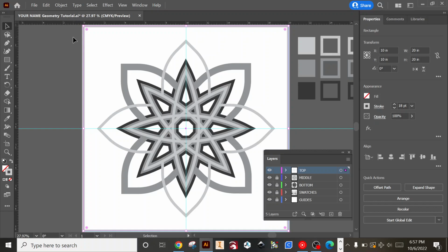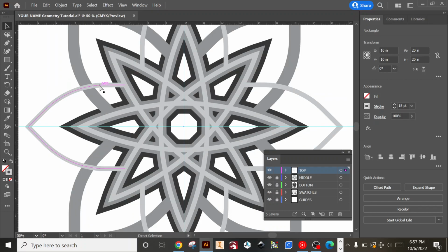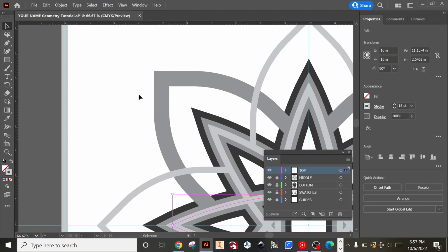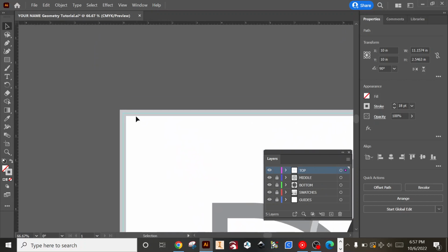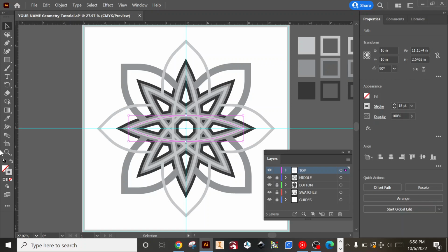Now, if you look really closely at this, the rectangle is actually hanging out over the edge. So if I go Control plus, Control plus, Control plus, and then I grab, I'm using the middle mouse button to use the hand tool. You see this light blue line, that is the outside of our board. So this outline is hanging out over it. So we actually want to select, I'm going to go Control O again. We're going to grab the eyedropper tool, and I actually want to select this guy, which is the inside stroke.